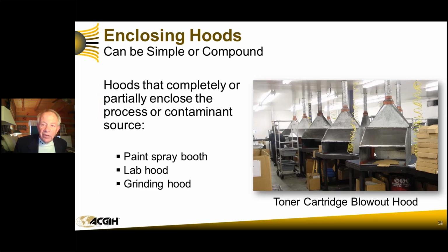We will get 100% of the contaminant, and now 1, 2, 3, 4, 5, 6, 7, 8, 9, 10. 10 of these machines is 3,500 CFM. A small 16 cartridge collector was used, and it was very successful. Look, this is a year into it. Find me some black dust. Tony's cartridge dust is black, and there you can see it on the back. It's very successful.